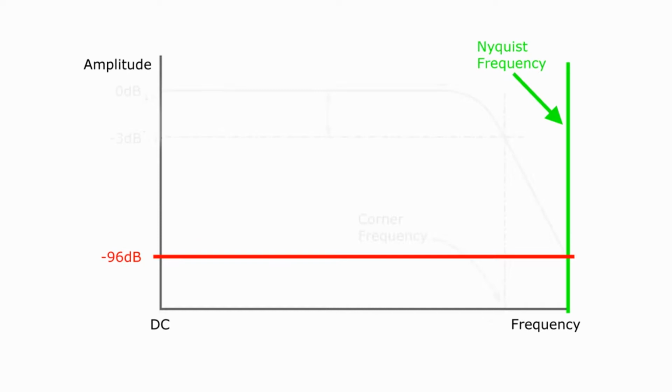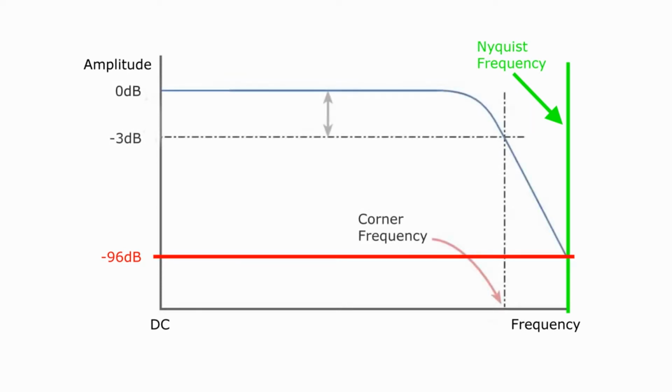The optimal setting for a low-pass filter corner frequency is positioned so that the end of the attenuation band is at the junction of the ADC's lowest resolvable amplitude and the Nyquist frequency. A common mistake is to set the corner frequency at the Nyquist, allowing resolvable although attenuated frequencies to be sampled erroneously by the ADC, unless, of course, one is aware of the consequences and prepared to differentiate between the real signal and the potentially resulting artifacts.